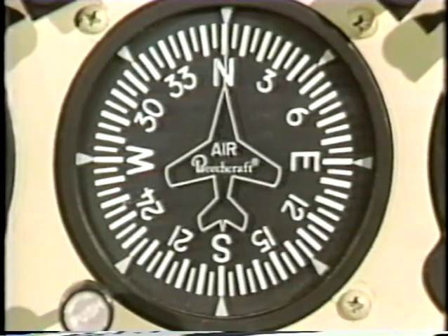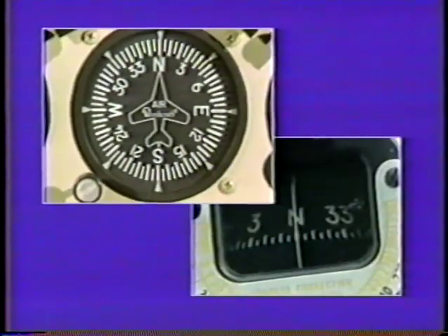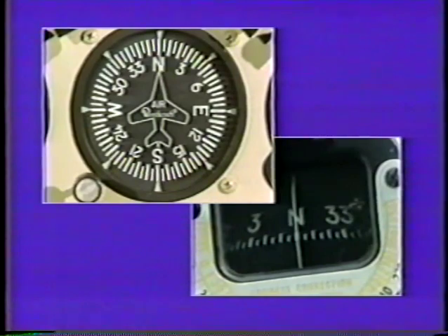The 3 represents 30 degrees, 6 is 60, 12 is 120, and so on. Each of the 30-degree increments is divided into smaller 10 and 5-degree calibrations. The heading indicator is used in conjunction with the magnetic compass and is periodically checked with and set to the compass reading. We use a gyroscopic heading indicator during flight to maintain headings, to facilitate reading heading information during turns, or while in rough air.